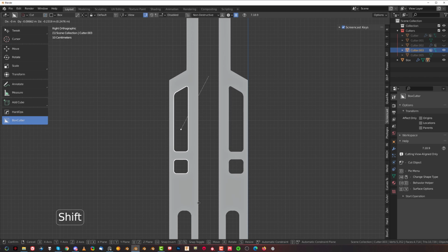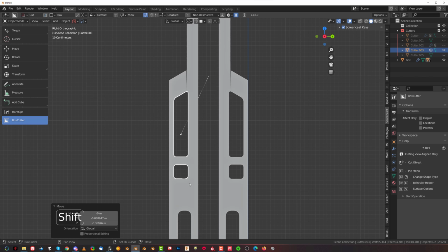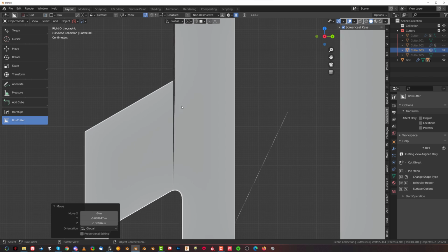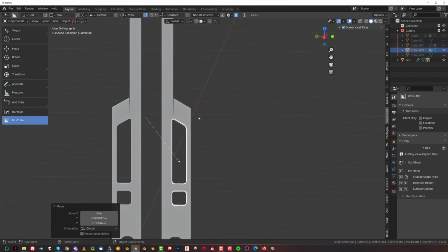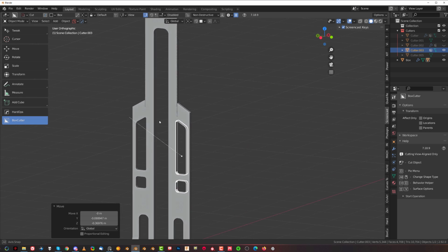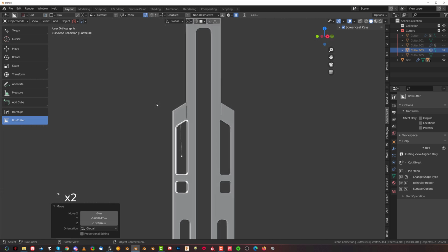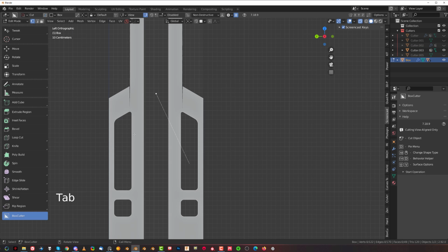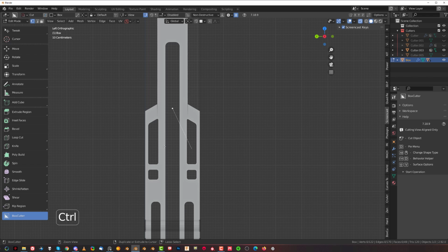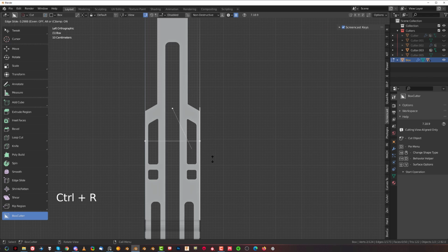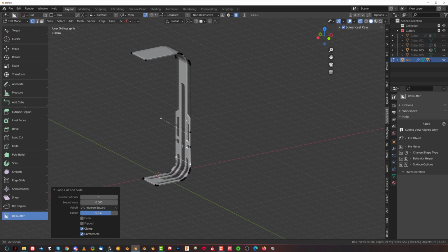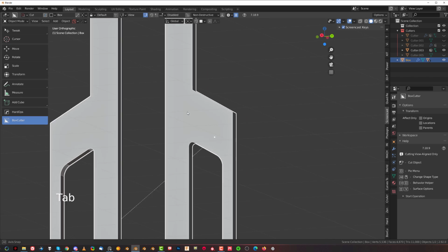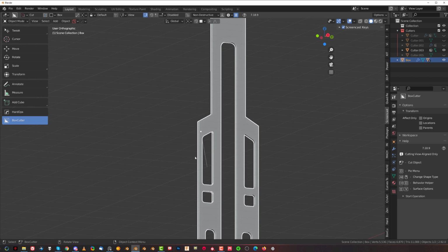Maybe we could move it somewhere down here. See what we're getting here, this shading problem? That's because of how Blender is going to be connecting this cutout to the shape. So we need to run our custom edges. So let's select this shape, go to edit mode and Control R and insert a loop, and simply insert a loop here, insert a loop here, and you can insert another loop here, and this should solve our problem. Cool, this should be fine. So now this thing is gone here because we created an edge here.